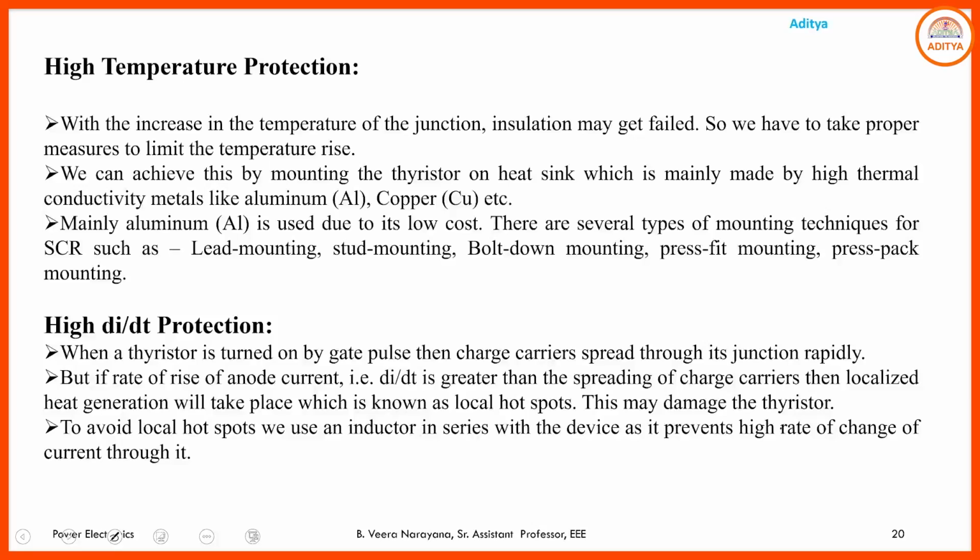And next one, high temperature protection. With increase in the temperature of the junction, insulation may fail. If the junction temperature exceeds a certain value, then insulation failure takes place between the power semiconductor layers, and the SCR may go to the damage.